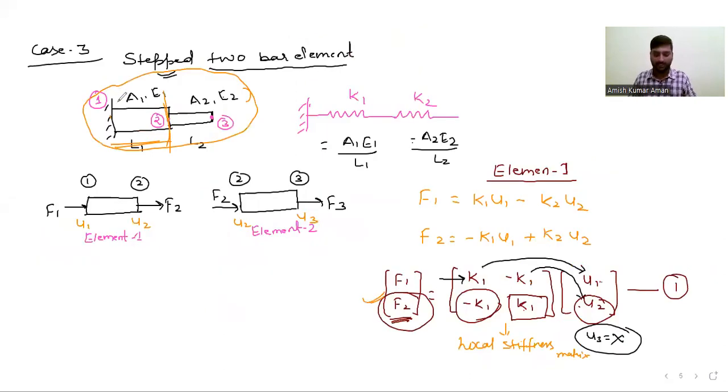I have taken the fixed support, right? So in this case, if I have taken the fixed support, what does it mean? It means the displacement at node number 1 is 0. There will be no displacement, because fixed support means what? It won't allow the element to displace in x direction, y direction, or even rotation also, moment also. So the displacement will be 0.